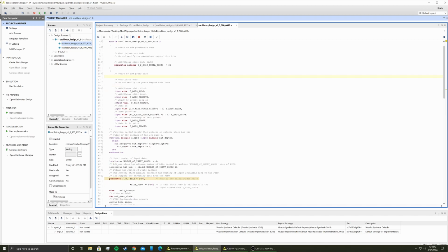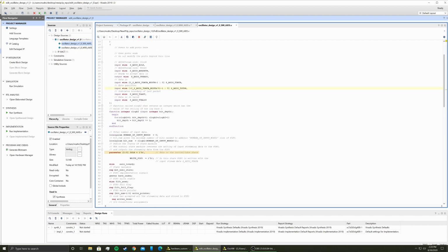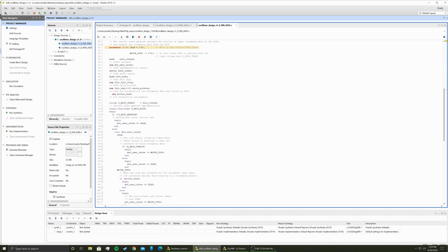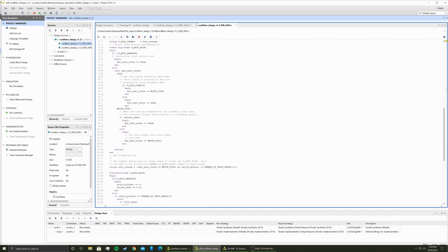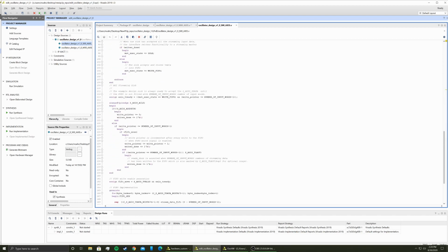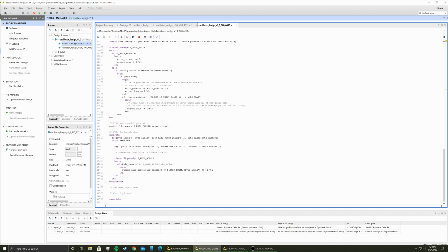This also runs on a clock, reset switch, data width, etc. This pretty much tells you what you're going to get as a data input. It works very similarly to the master port, however, it's just going to receive data from whatever it's connected to. Unless you would like to specifically write something such as in the stream data FIFO at the very bottom, it's not really required for you to change this.